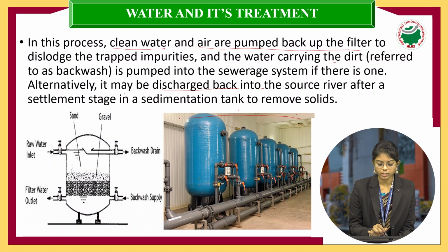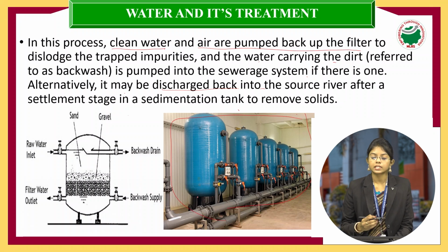So you can see filters like this. We are going to send the water from sedimentation to filters. Here in the filters, we are going to remove all the solid particles. So the water is passed through the sand and gravel beds, so that the solid particles which are not removed in the sedimentation tank can be removed in the filtration tank.